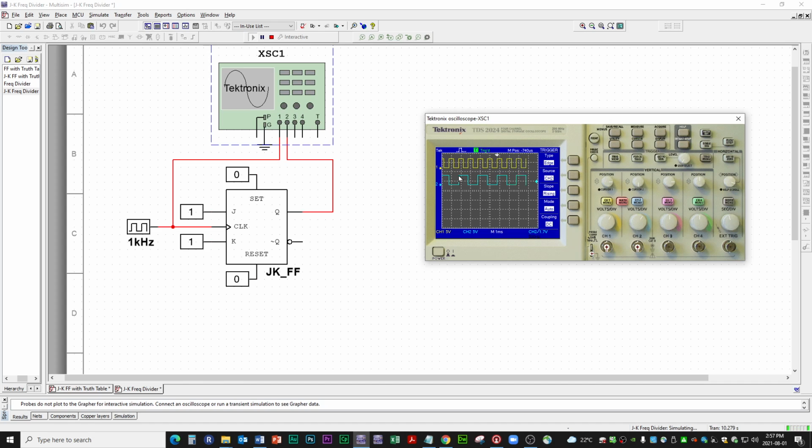So here's on, positive edge, and the positive edge changes, but it's off. And it is on again. We have to wait 2 cycles before it completes 1 cycle. So this frequency is half of this frequency.